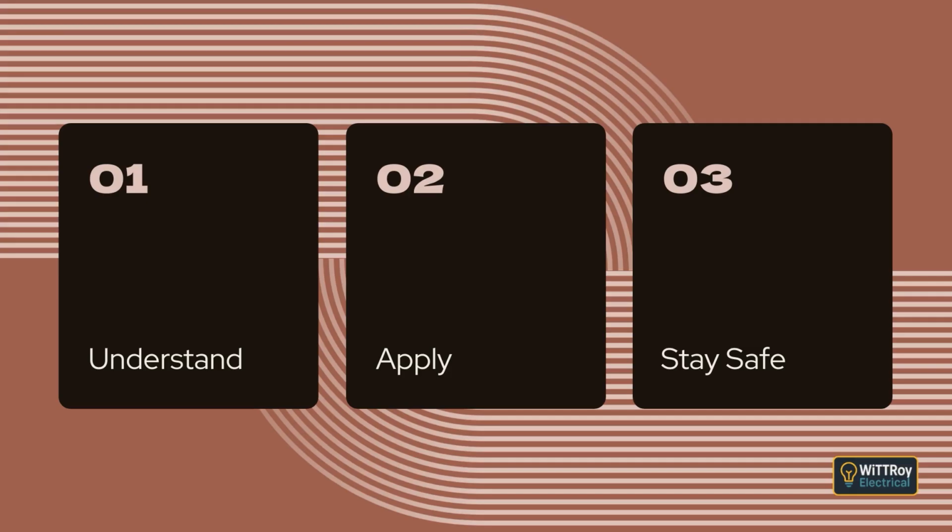Clause 3.9.4.2 Wiring systems near building surfaces. Wiring fixed in place by fasteners or passing through structural members must be protected by one of the approved methods if it is less than 50 mm from a wall, floor, ceiling, or roof surface. Protection is also required where the cable is located more than 150 mm from wall-to-wall or wall-to-ceiling corners. These requirements do not apply to wiring systems that can move freely enough to avoid being struck by nails or screws driven into the surface.